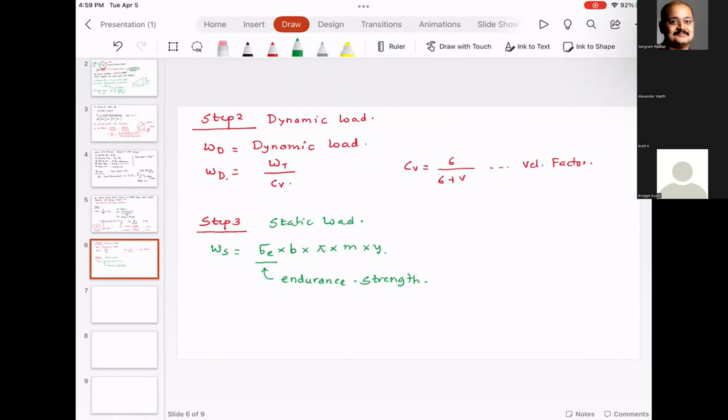And typically, when you are looking at wormwheel design, the worm is made up with steel, and the wheel or the gear is typically made with cast iron or phosphor bronze. And here is the reason why.